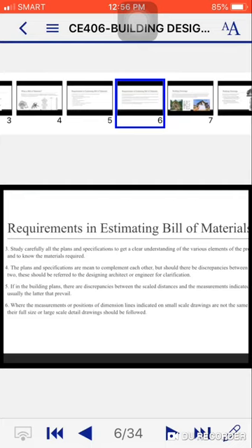So the project working drawing plans and specifications should be carefully studied and a checklist of the materials to be determined drawn up. So the computation work should be done in an orderly and systematic manner and recorded in computation sheets. So this will facilitate easier reviewing or checking of calculations made either by the estimator himself or by others. So another advantage of using worksheets is that repetitive computations are reduced to a considerable extent. So here we use Microsoft Excel, or if you have any program for estimation, it will make our lives easier because it will no longer take up time.